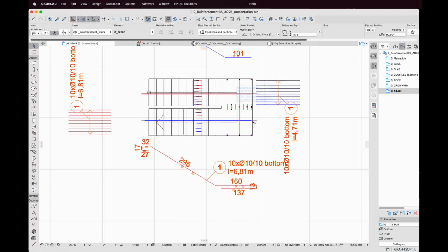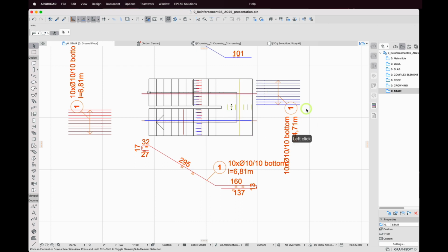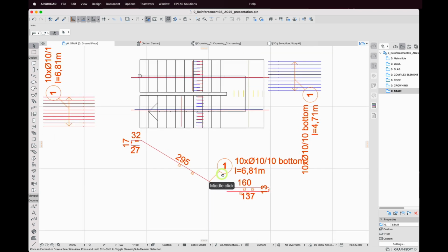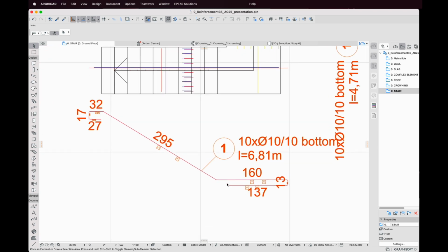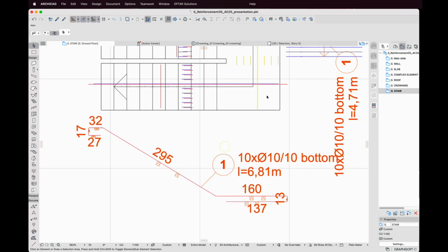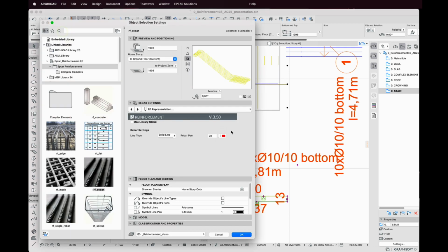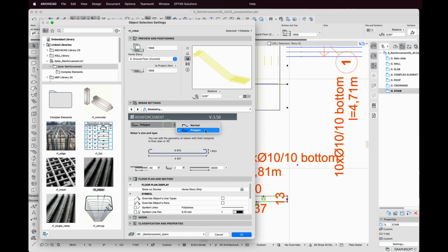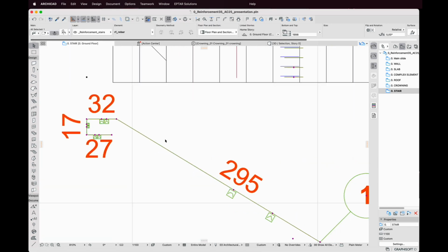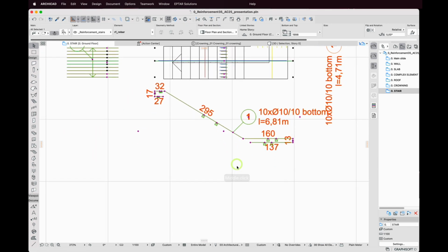There are some simple rebars already placed, but now I will place custom rebars into the inclined stair. In the reinforcement solution, I can select the special rebar. I select it and we can see that it is not a standard element. I open the settings window for it. On the Geometry tab, I can select the polygon option from the list. Next to this, the new option appears where I can define the editable hotspots number on this element. I will now show how it works.